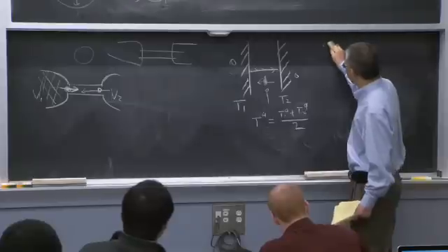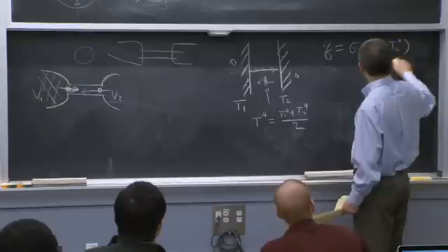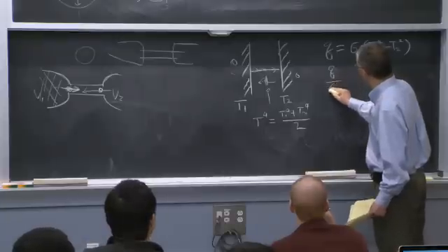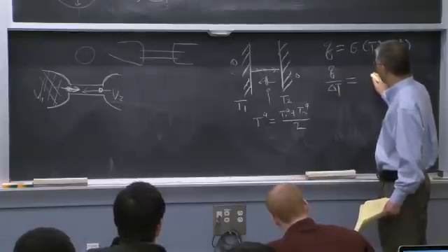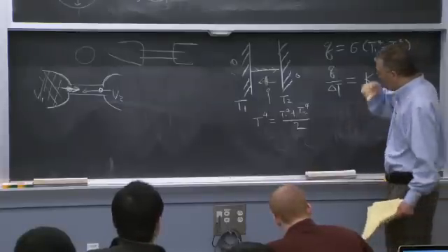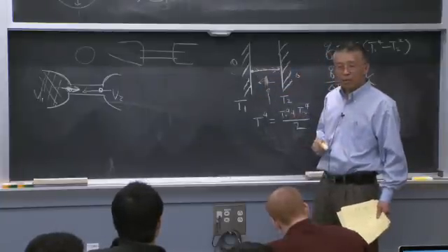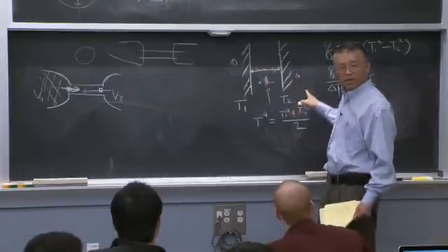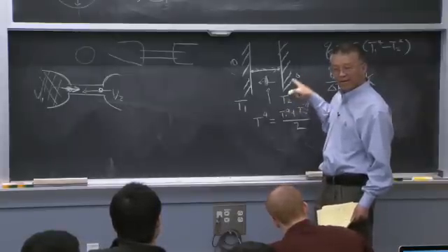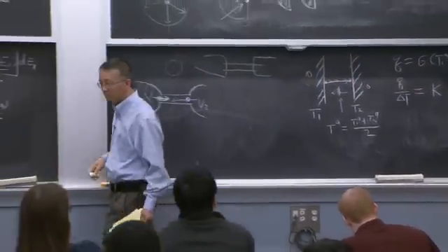So when you do your black body, you say Q equals sigma times T1 to the fourth minus T2 to the fourth, right? And correspondingly, you do your Q over delta T, that's your conductance, right? It's not infinite. However, if you are able to put a detector and measure this point and this point, it's the same temperature, so you should get an infinite conductance, right? So it depends on how you define it. You have to be careful. That's my point. Okay? I'll stop here.